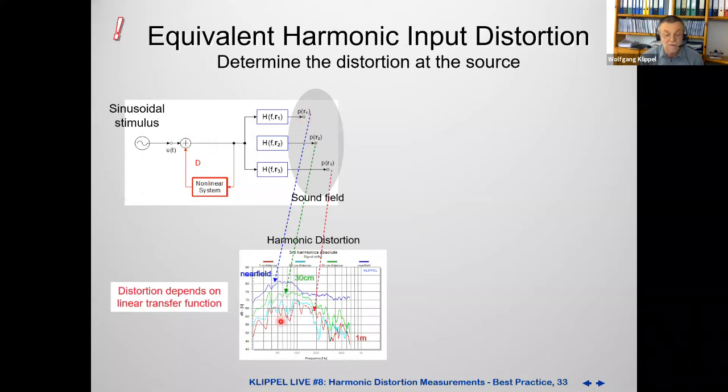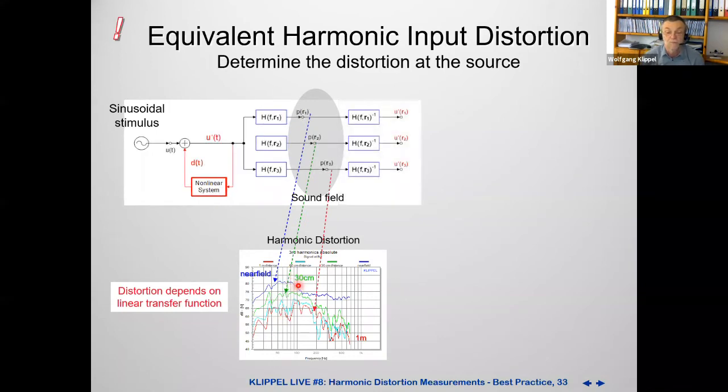That generates different curves from the absolute harmonic distortion components. By the way, if you are dividing that by the different fundamentals, it becomes even more complex. Now, what is the idea? Removing this shaping. That's more or less what we have also done here, removing the room influence with a simulated free field condition.